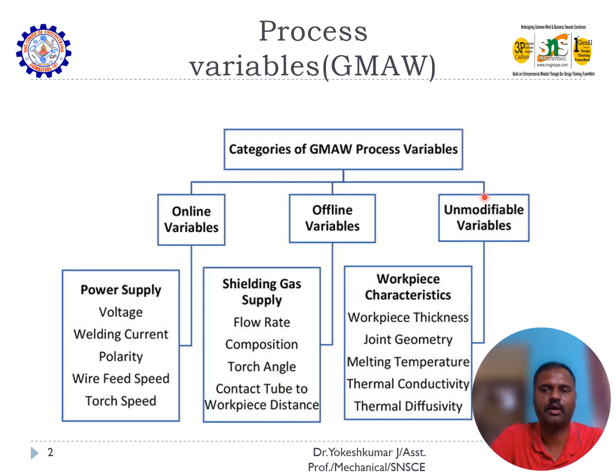Then unmodified variables, that is workpiece characteristics: the composition of the filler metal, melting temperature, thermal conductivity, thermal diffusivity, joint geometry, etc. These are all customer requirements, so we cannot change them.